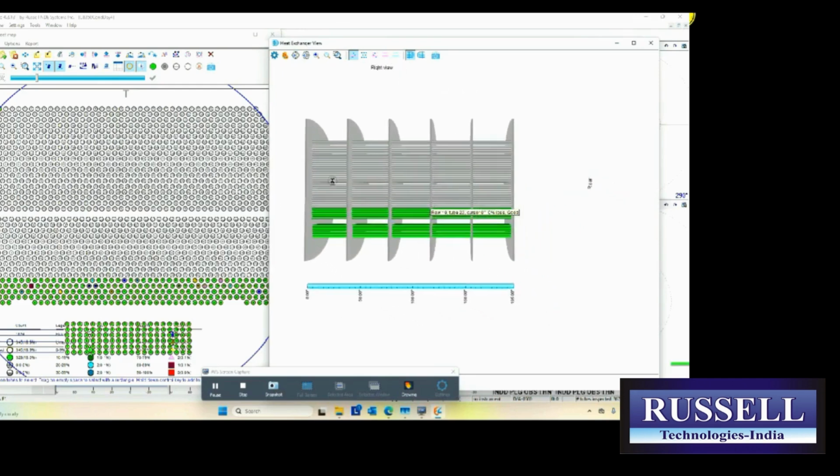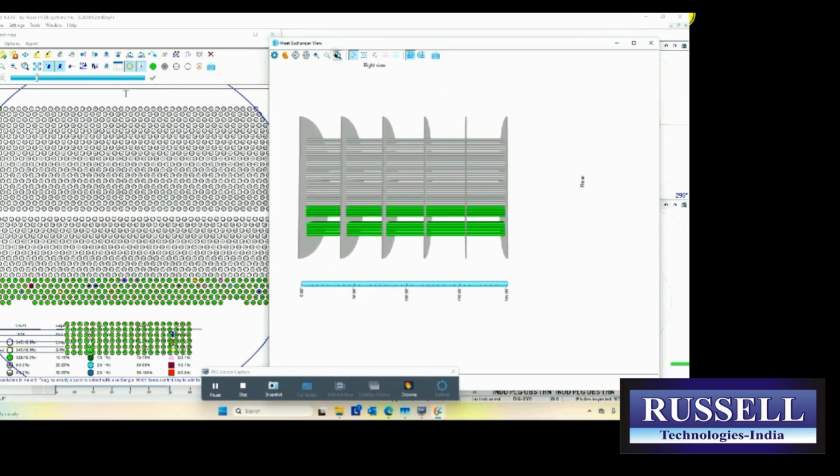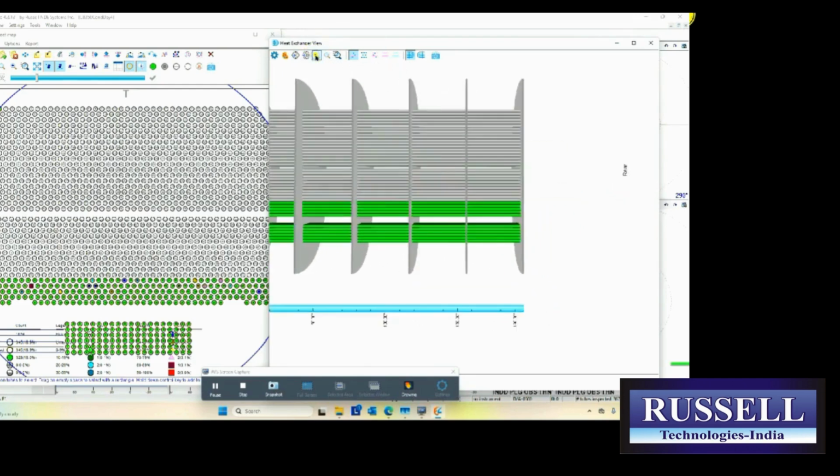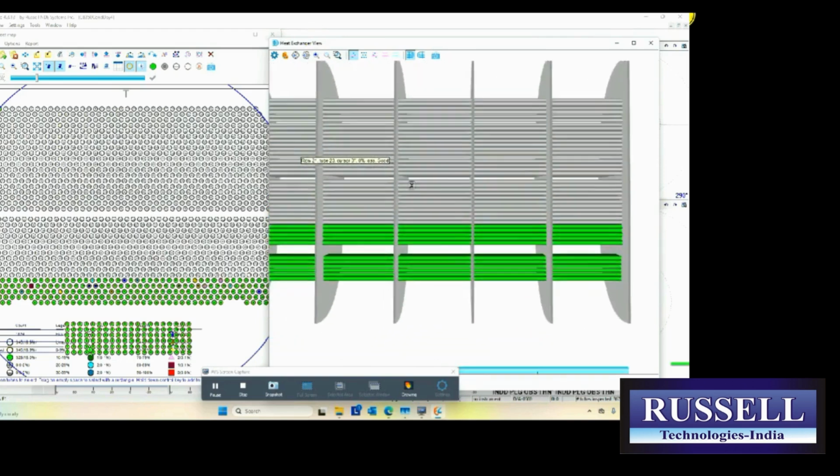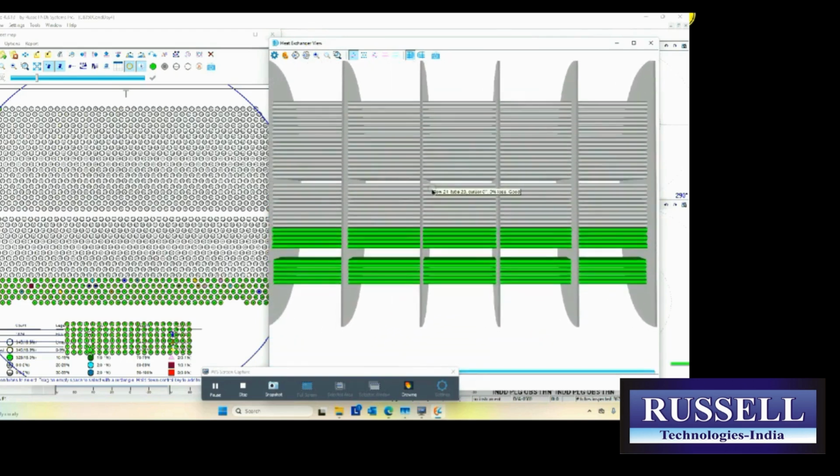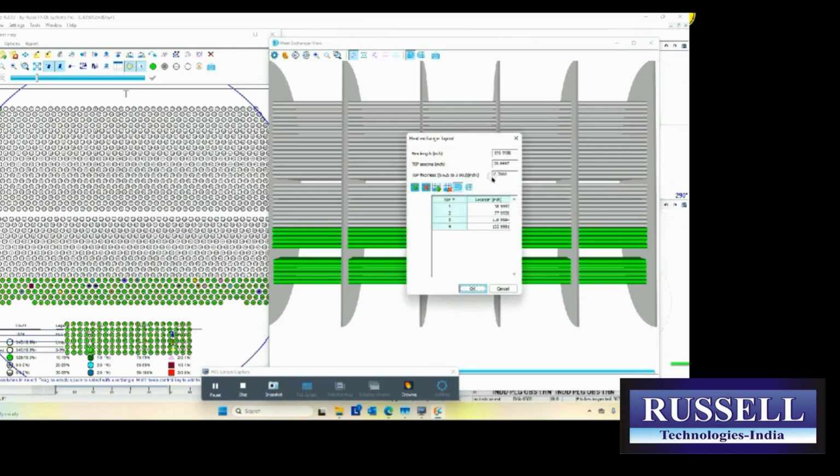tube support plates. And if we zoom in on this, you can zoom it, you can move it around with a right click and drag. You can change the position of these tube support plates by accessing the settings menu and changing these values. So the heat exchanger length, the tube support plate actual spacing in inches, and the tube support plate thickness measurement.